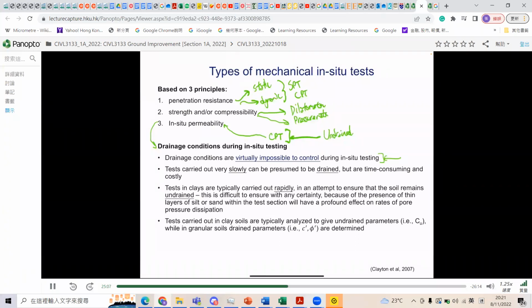The second thing is we often can assume drained conditions only if we carry out the rate of penetration, for example, or loading at a very slow loading rate. And this rate of loading would be so slow that it would not be pragmatic in the field. It'd be extremely costly to have a rig moving millimeters in penetration depth, let's say in an hour, right? We can't afford that. So it's not practical. So we do have to make some assumptions here of whether it's drained or undrained. And we have to forego the conclusion that, yeah, it's probably somewhere in between in reality.